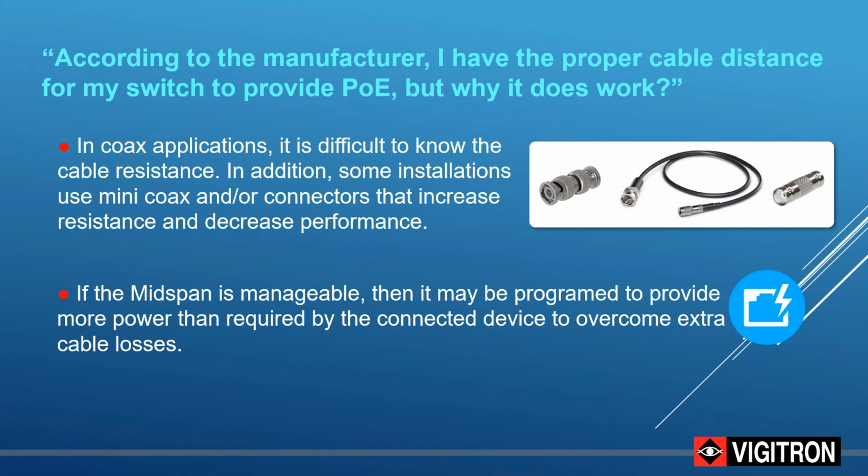The casino did not want the cabling pulled. So what we were able to do was increase the amount of power and use a mode called force power. Now, if you've participated in any of these other seminars, you know that the term force power could be called an injector. And we all know that we don't want to use injectors because injectors don't have the safety factor within the IEEE standards for PoE. And should there be a short, there's no way to turn the power off except by having the power source burn up or the connected device.